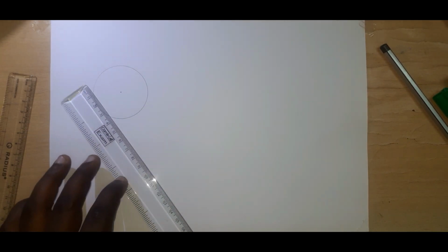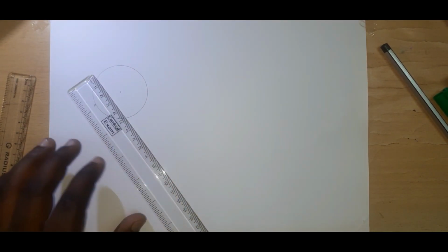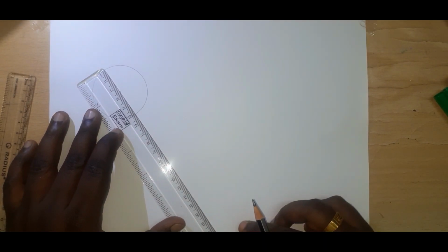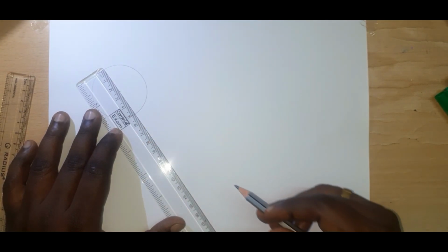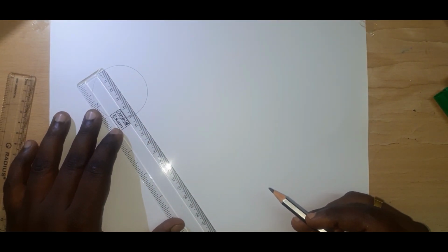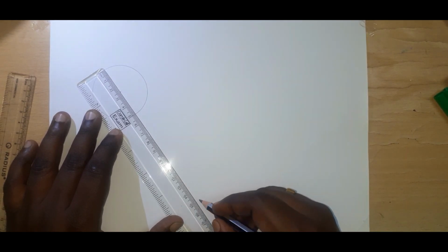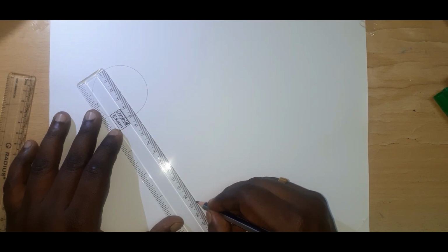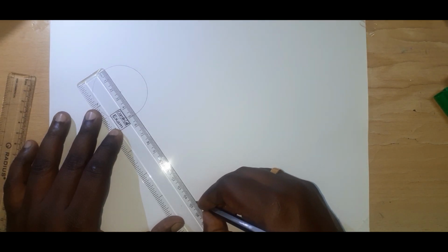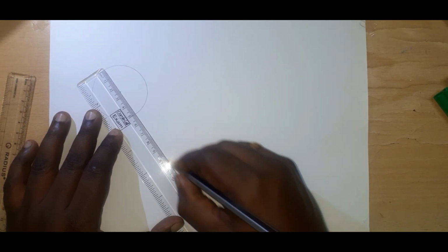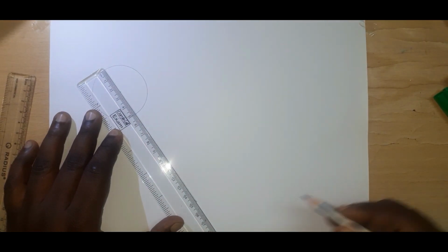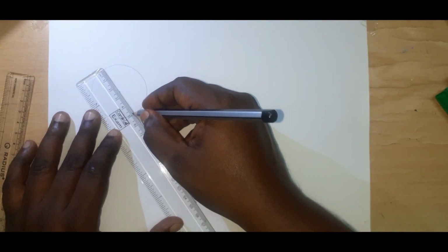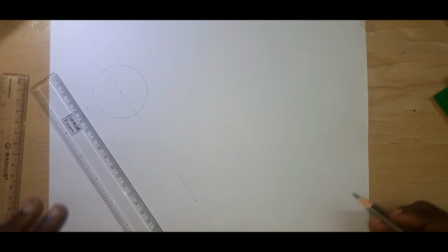For the directing circle I am going to draw an inclined line. Look here, through this diameter it will cross at this point. The directing circle diameter is given as 200 mm, so the radius will be 100 mm. Now the total value will be 150 mm: 100 mm plus the 50 mm diameter. So here the 100 will be there, and above that the circle will be there. So this is our diagram.